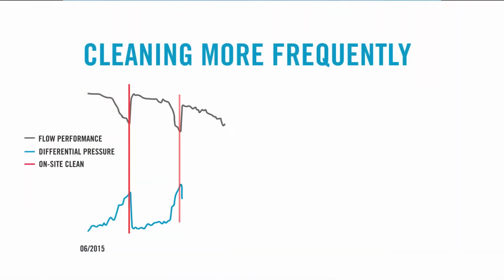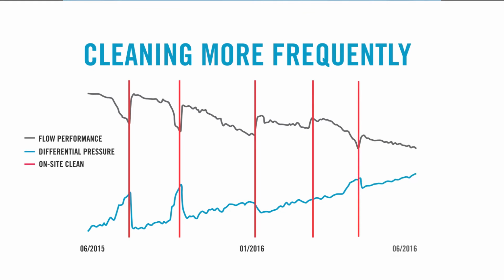Today, we will be discussing the troubleshooting measures we use here at Avista to diagnose problems, find solutions, and apply them on site. The example for this presentation is a municipal site that is using a well water source and has had a past history of biological fouling issues in their break tank. They started to see rises in delta pressure in the reverse osmosis system and an excessive cartridge filter replacement. Additionally, their high pH cleans for the membranes were no longer effective, and flows and DP were not returning to startup conditions.